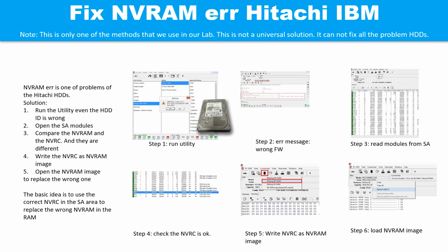Now the drive gets into ready state. Perform standby command. Step 5. Remove the isolator. Try to read the hard drive ID. Step 6. Relaunch the utility. Step 7. Create backup, clear HDS, and read the user data.